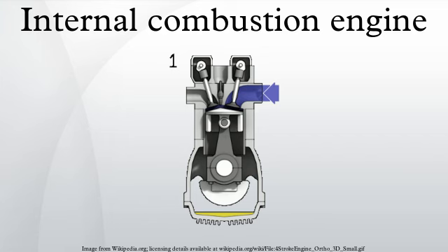Large diesels can run with air mixed with gases and a pilot diesel fuel ignition injection. Liquid and gaseous biofuels, such as ethanol and biodiesel, can also be used. Engines with appropriate modifications can also run on hydrogen gas, wood gas, or charcoal gas, as well as so-called producer gas made from other convenient biomass. Experiments have also been conducted using powdered solid fuels, such as the magnesium injection cycle.